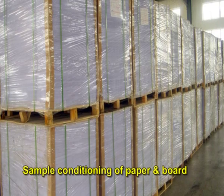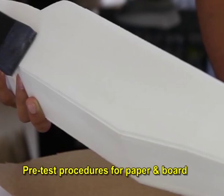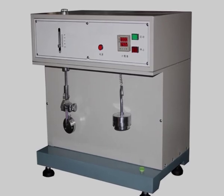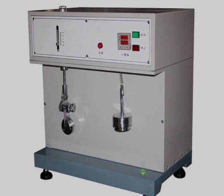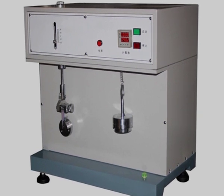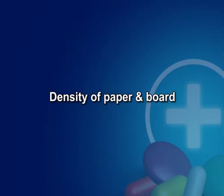General test for paper and board. Number 1. Sample condition of paper and board. Number 2. Pre-test procedure for paper and board. Number 3. Moisture content. Number 4. Folding endurance using various instruments that fold the test piece back and forth through a specified angle until rupture occurs. Applies to all forms of paper and boards, but there may be different instruments for different boards. Number 5. Density of paper and board.